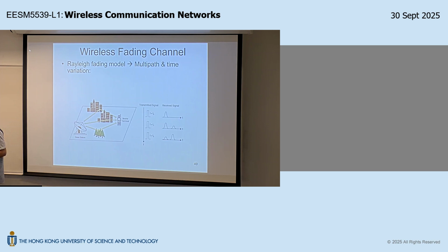So that would be the scenario in terrestrial propagation due to the multipath effect. Different locations will experience different types of superposition. When you are at the spots where you have constructive superposition, then you will receive high power. When you're in a location where you receive destructive superposition, then you will receive low power, right? You may not receive 0 because all these multipaths may not have the same amplitude. But once you have mutual cancellation, the resulting signal will be much weaker. Is that okay? So that would be the effect of so-called multipath fading.